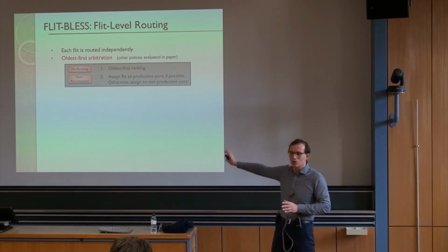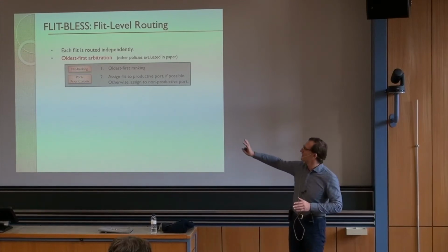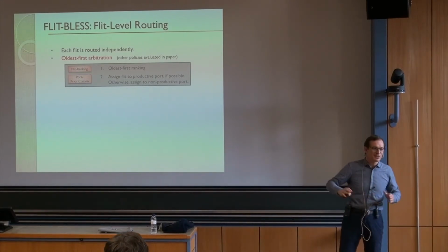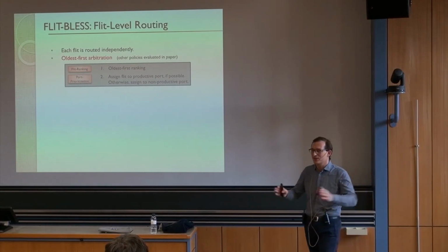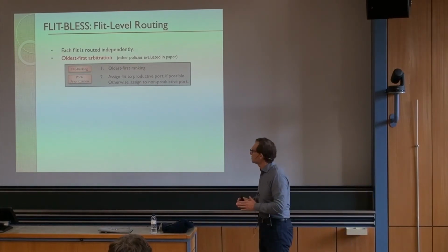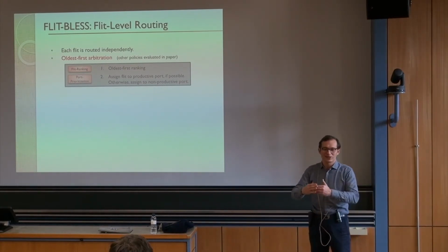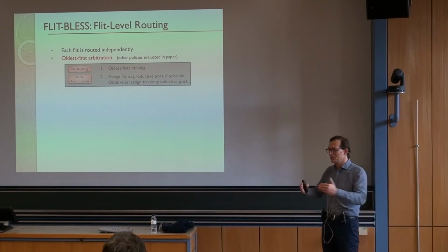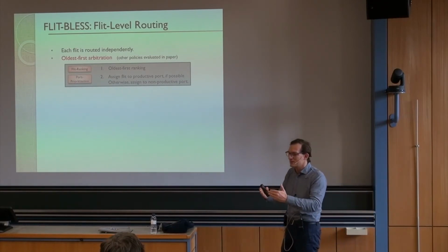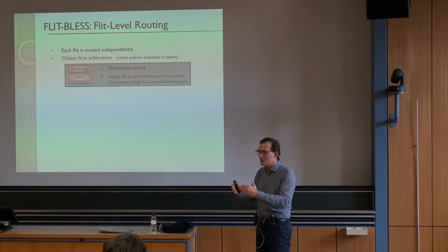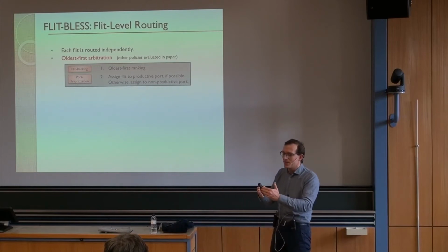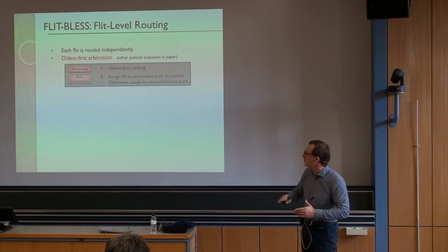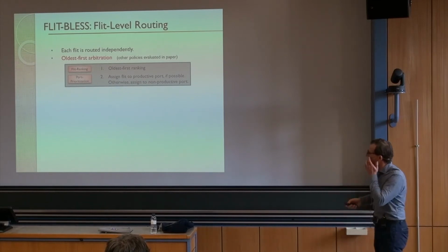The paper discusses WORM, which is interesting, but I'm not going to talk about that. Basically, how do you do wormhole routing in a bufferless network? Not so easy, because you need to break the worms sometimes, since you cannot buffer anything. Sometimes the body flit needs to become the head flit in a worm. But you can read the paper for more detail on that.